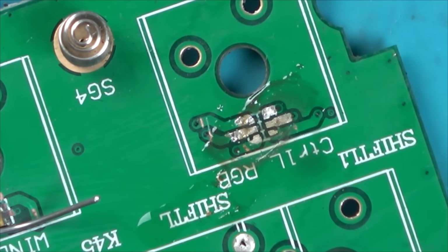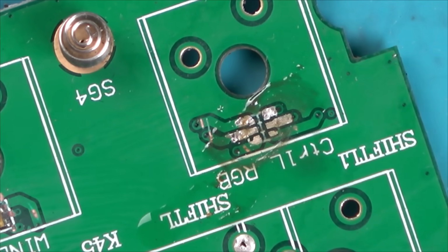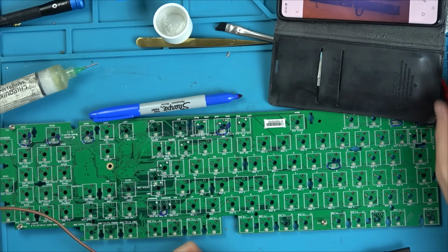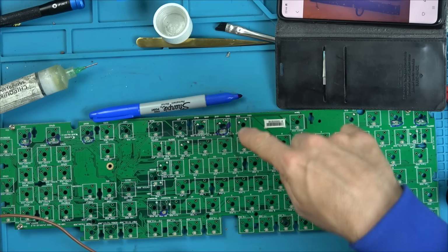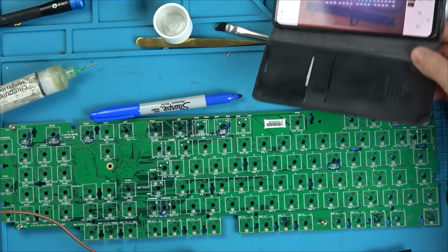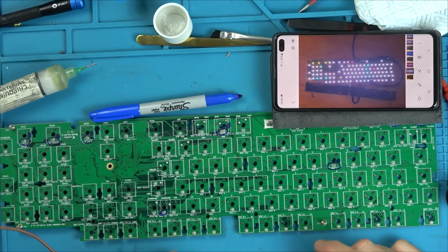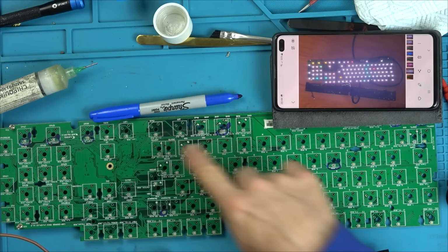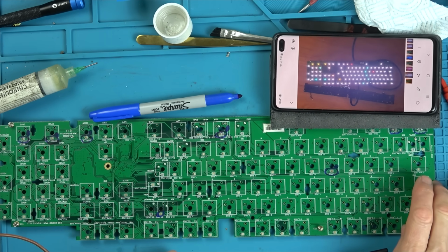Yeah. Well, I'm going to place that LED back on purely because I want to make sure I know what orientation it goes in. Right, okay, I've been going across them and I think I only need to replace 1, 2, 3, 4, 5, 6, 7, 8 of them. So I took a picture of when it was plugged in just now, and all of the ones that are cyan are testing okay. All of the ones that are yellow, red, and these two that are completely dead now, are not testing okay.